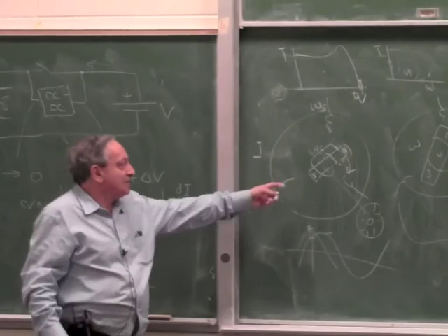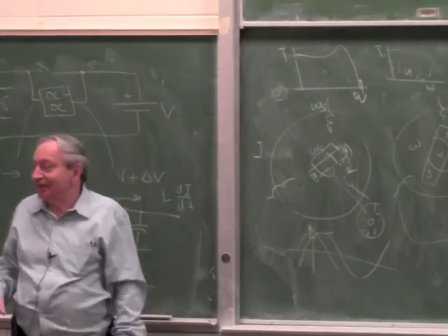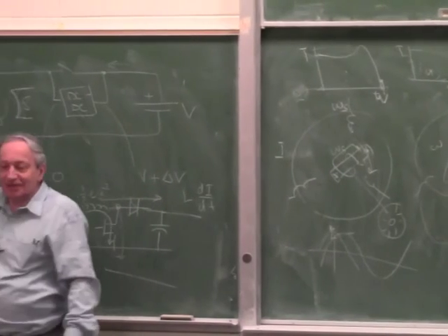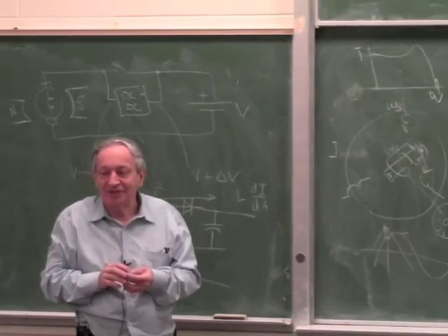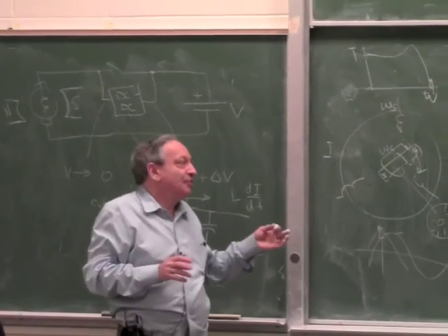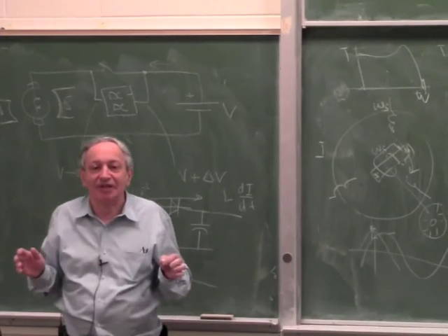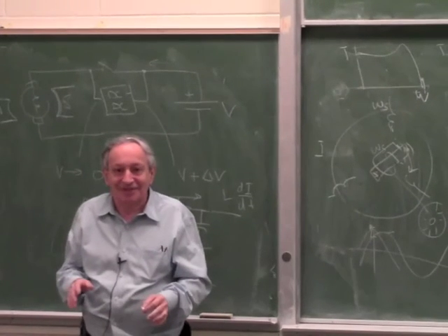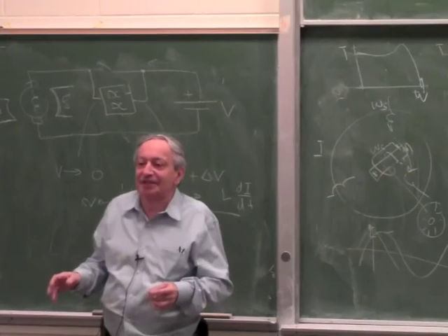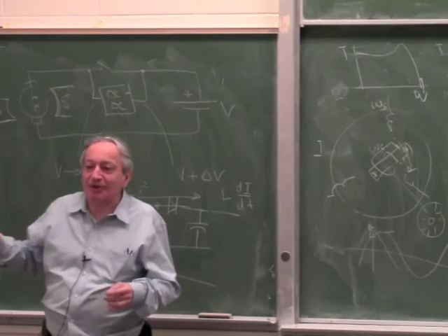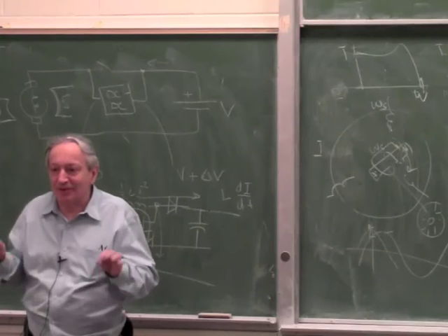Because this one, the induction motor, doesn't have a magnet, and this one doesn't have a magnet, but it still can feed power back to the grid, and this is only important in big systems, or systems which have to be super efficient, like an electric bike. But in a normal servo, unless it's a multi-horsepower servo system, you don't bother with it.